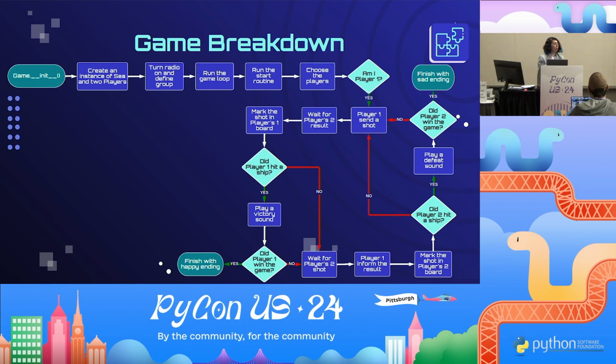Yeah, but we are going to be communicating from one board to the other using radio. So we have 2 instances of players. One is going to be me, the other one is going to be the opposite. Both boards are going to have the same code running, but we are going to have logic to define who is player 1 and who is player 2. So first of all, we define our group, because we are going to be using the radio. We run the start routine, as we did before, the one where everyone is ready to play. Then we are going to choose the players, which is the first function we are going to be doing now. To choose the players, one of them presses button A, that is going to be player number 1. The other one presses button B, and is going to be player number 2. So you need to coordinate with your partner who is going to be the first player and who is going to be the second player.